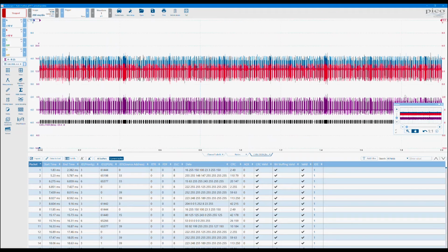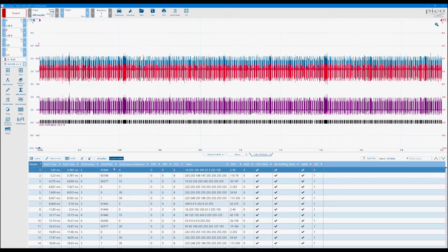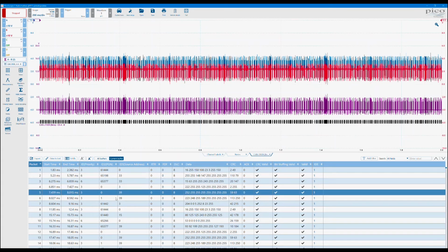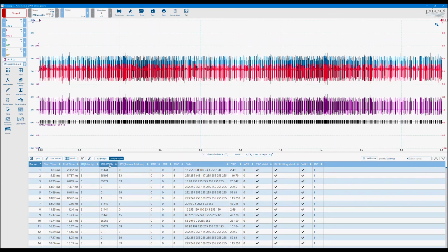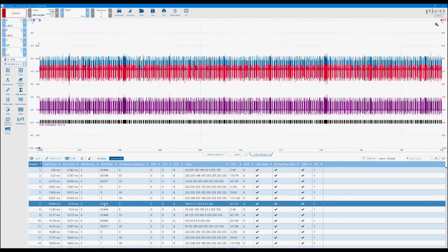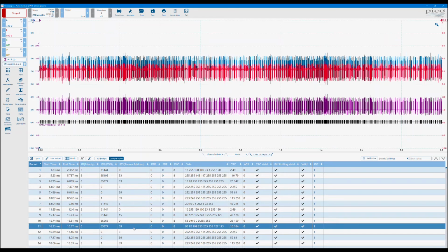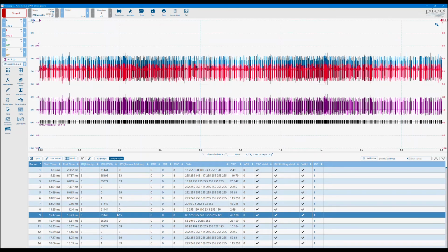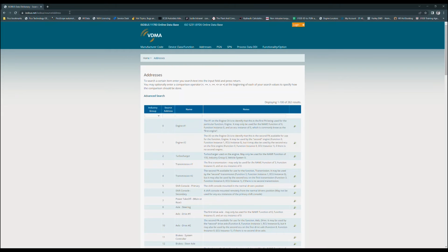Okay, right, let's zoom all the way back out again. So providing that we have all of our decoded data listed underneath. Now, as I said in the video, I have mentioned that this decoder is set up into decimal. The reason being, obviously, is that PGNs typically come in a decimal format, and it also means the source address will be in a decimal format as well. The website I mentioned was the isobus.net website.